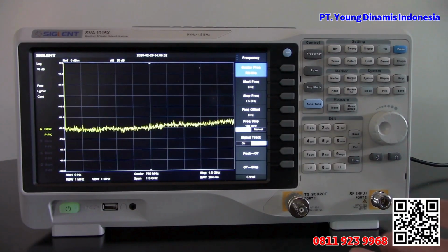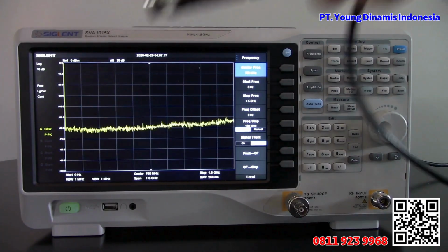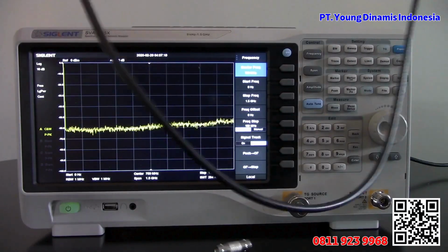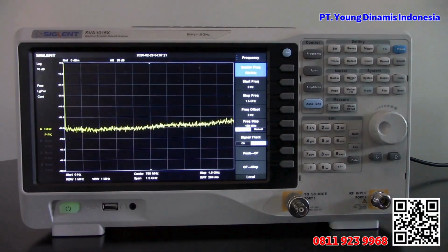Another technique is time domain reflectometry. Frequency domain reflectometry has some advantages in its position accuracy. It does have some limitations as far as the length, but if you're looking at cables around 100 or 200 feet, this is going to get you within a few inches of that fault. So that is a really, really nice place to start when you go hunting for a few hundred feet of cable for that problem.